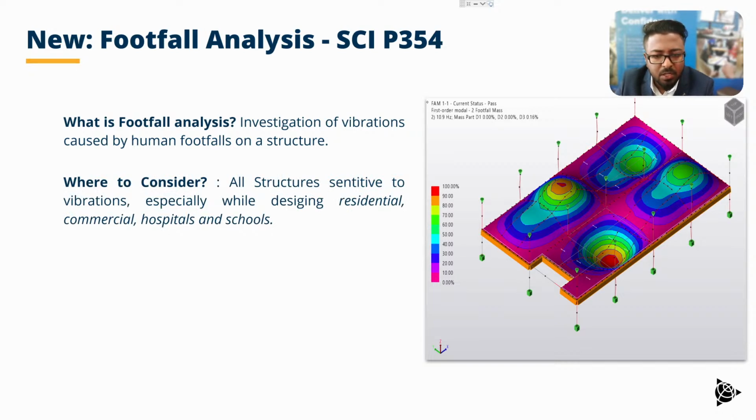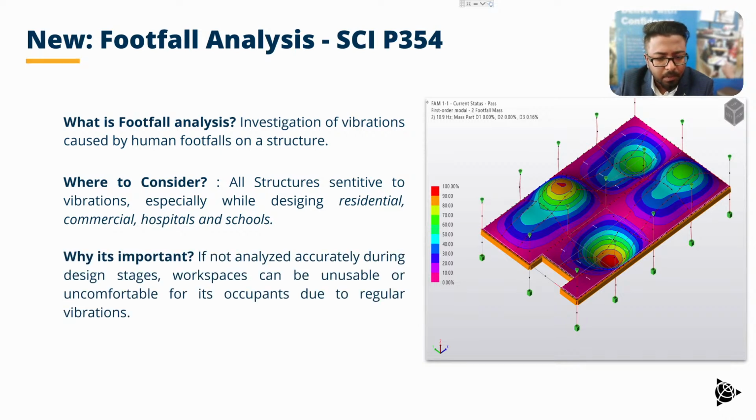When you ask why it is so important to include this design calculation: human footfall is a significant source of vibration, and when its adverse effects are not assessed accurately during the design stage, the building would be susceptible to vibrations, which would make the workspace unusable, or sensitive equipment can't be used, or it could make the occupants uncomfortable.